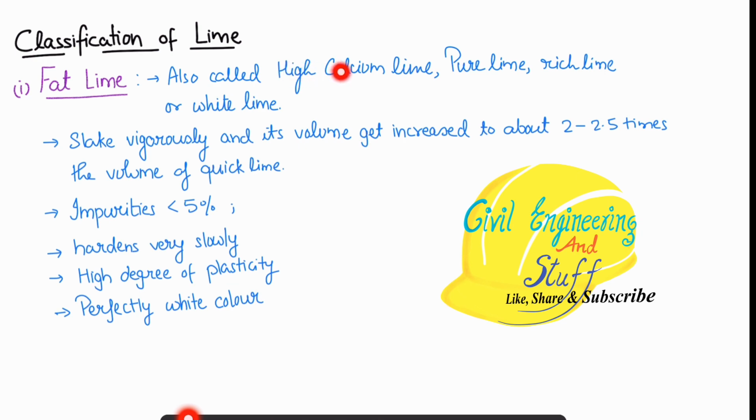That's why it is called high calcium lime, pure lime, rich lime, or also the white lime. That is the name for the fat lime, and fat lime is the purest form of lime. Since it is the purest form of lime, the slaking process is very vigorous. Upon the addition of water, a lot of heat is evolved and hydrated lime is obtained. It slakes vigorously and the volume increases